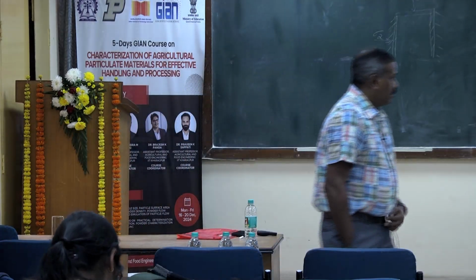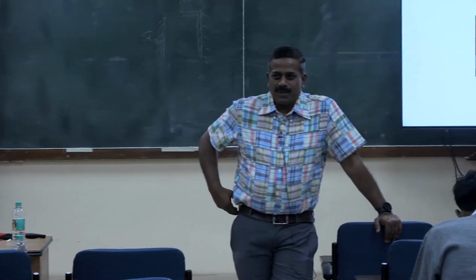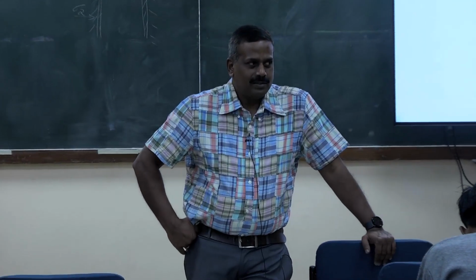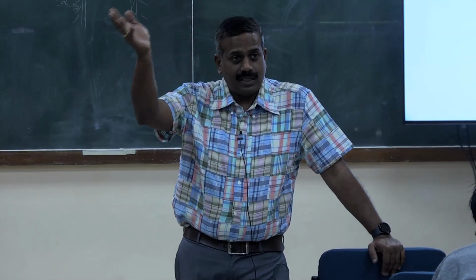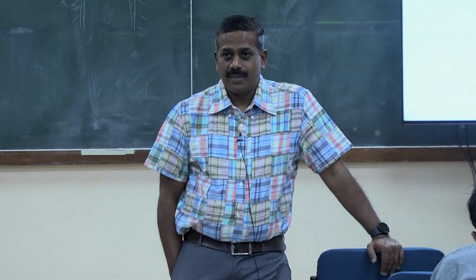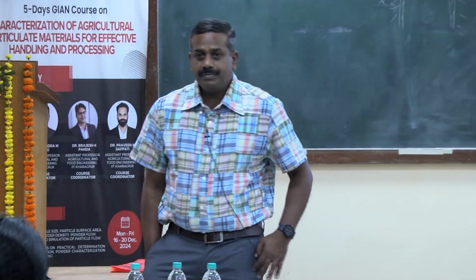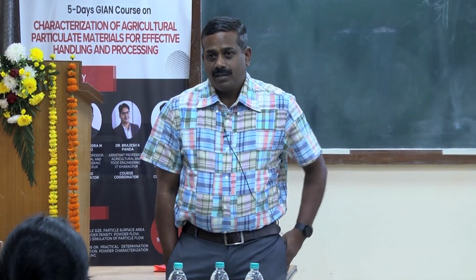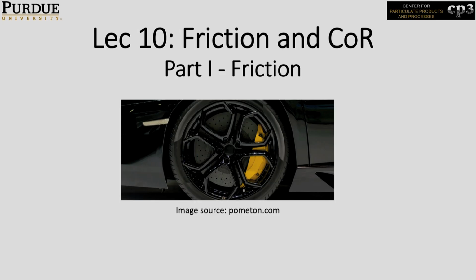Okay, so if not, we'll talk about coefficient of restitution. It might be useful for you for coefficient of restitution and friction too, right? We talked about angle of internal friction, static friction coefficient, etc. That's used in the pressure calculations, right? We will not use angle of internal friction here for most of the stuff, except for powder flow and bin design, hopper design, etc.